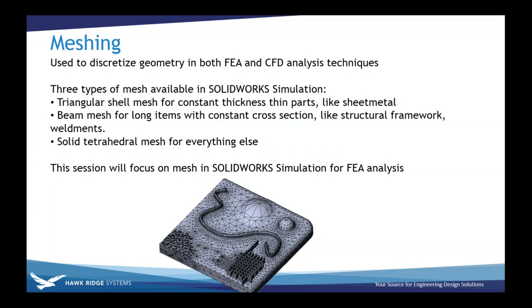Meshing is a fundamental component of everything, well, of most analysis tools. There's a couple of new meshless technologies that have been bumping around in the market. But for a tool like SOLIDWORKS Simulation, it's a fundamental component of every single analysis. No matter what type of analysis you're doing, if you're doing structural analysis in SOLIDWORKS, you're doing a mesh, whether that's exposed to you or not.